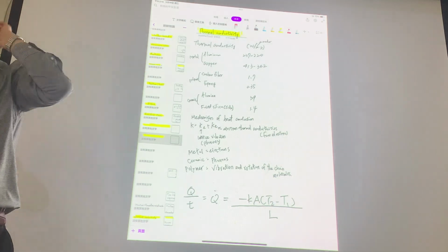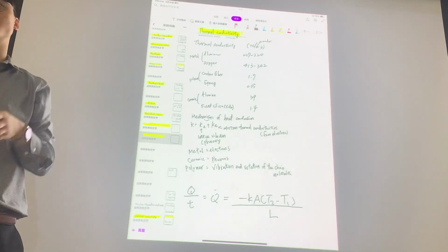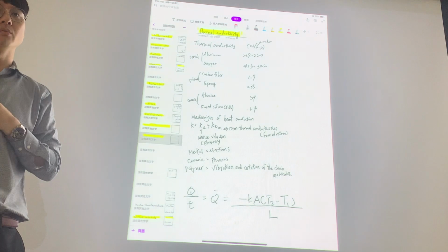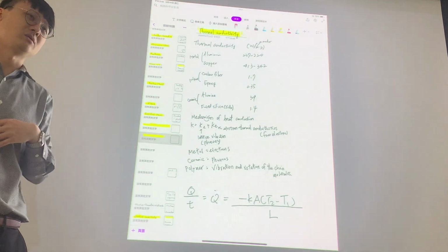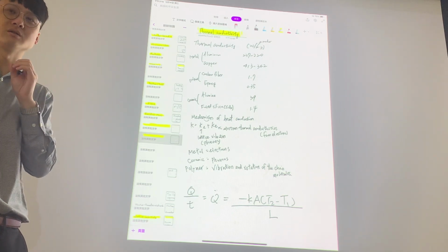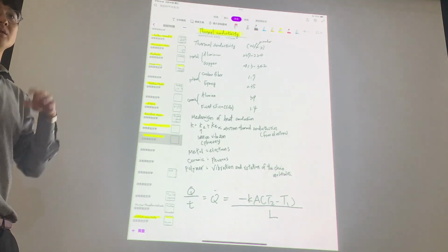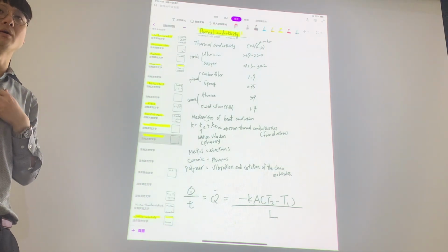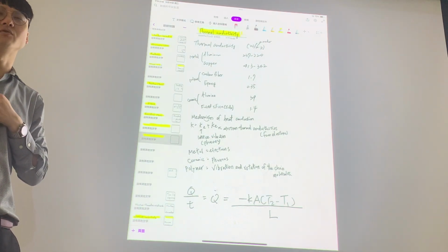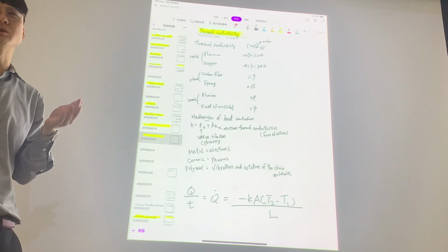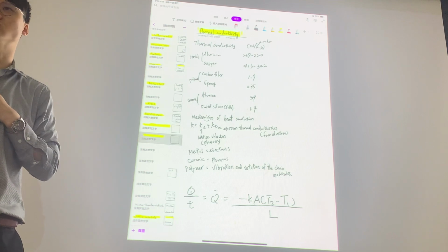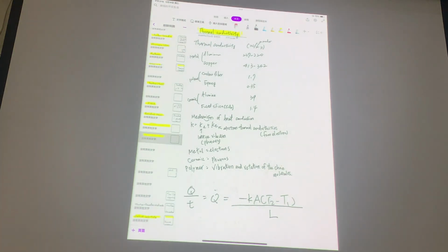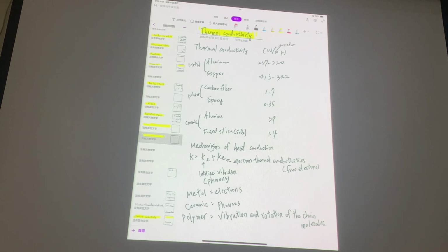So in the future, if you go measure the material thermal conductivity, you would expect a certain range. If you bought this ceramic, you would have a rough answer in your mind for its thermal conductivity. You have an idea of what a reasonable measurement is, right? If you measure ceramic, you should probably get 2 or 5, maybe 10. If you measure metal, it should be 100 or maybe 200. Does that make sense? That should be the number, right?